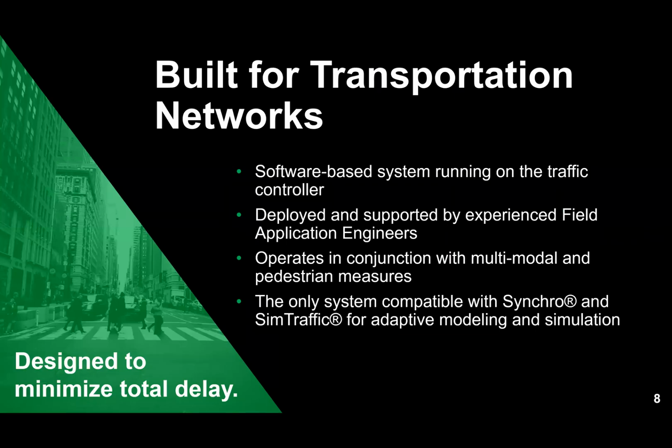Now let's talk about how SynchroGreen was built for transportation networks. SynchroGreen is a software-based system and it runs on the traffic controller. This is an important feature that allows typical signal operations to remain. And that's the difference between a software approach and a hardware approach, which I'll talk about in the next slide. So again, the adaptive program resides on the controller and it's not a separate piece of hardware.